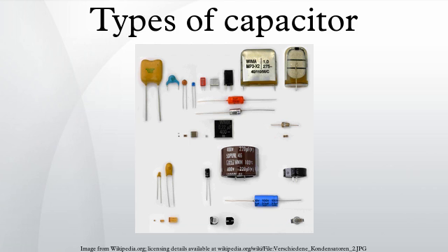The losses of film capacitors and some Class II ceramic capacitors are mostly specified with the dissipation factor tan δ. These capacitors have smaller losses than electrolytic capacitors and mostly are used at higher frequencies up to some 100 MHz. However, the numeric value of the dissipation factor, measured at the same frequency, is independent of the capacitance value and can be specified for a capacitor series with a range of capacitance. The dissipation factor is determined as the tangent of the phase angle between the reactance and the ESR, and can be shown as the angle δ between the imaginary and the impedance axis.